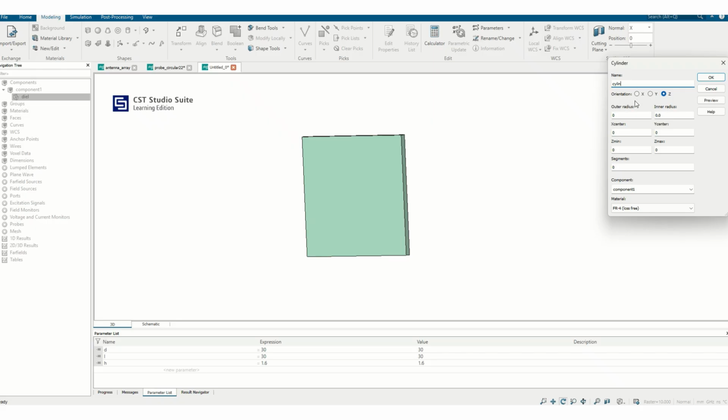This can be used to create any cylindrical structures or structures like a toroid with some inner radius. So let's start without the inner radius. Let's use an outer radius of 20, center x and y as 0, 0, and some thickness h.